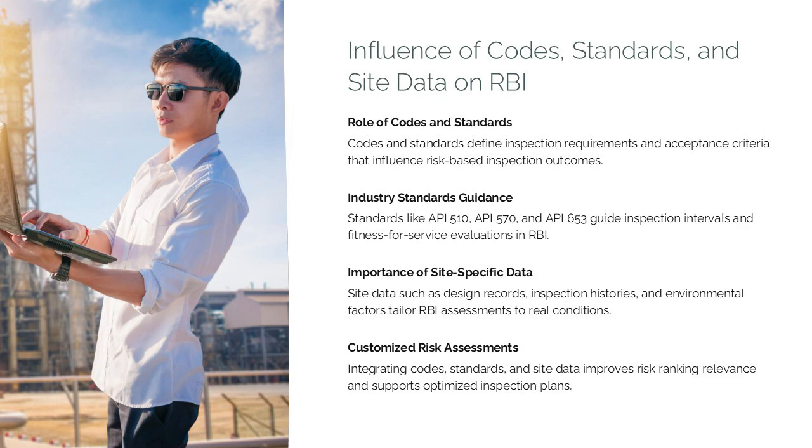In addition, process-specific standards may apply depending on the service environment, such as standards addressing high-temperature hydrogen attack, sulfidation, amine systems, or hydrofluoric acid service. Understanding and incorporating these requirements ensures that RBI assessments remain technically sound and compliant.